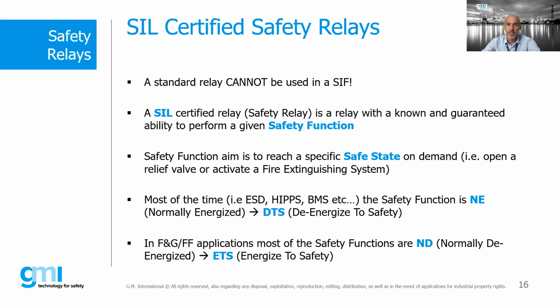Because a SIL certified relay is a relay with a known and warranted ability to perform a given safety function, you know what kind of safety the relay you are choosing is able to give. That is an important thing. Maybe the relay you are using is very safe, but it's not proven, so it's not certified, so it cannot be used for that function.